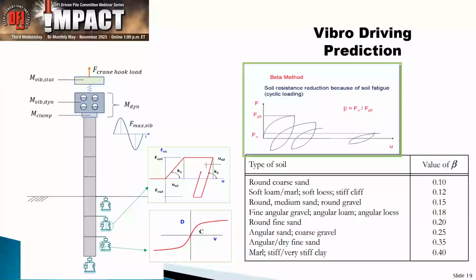And for the springs, most of the time we're using an elastoplastic soil model, where you basically assume that the first part is elastic, that you see over there, and then suddenly it goes over into a straight line where you have the plastic behavior of the soil. Not very realistic, I'll come to that in a second, but that is the standard model that we're using.